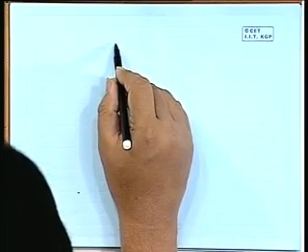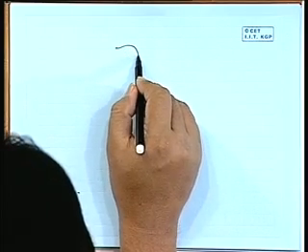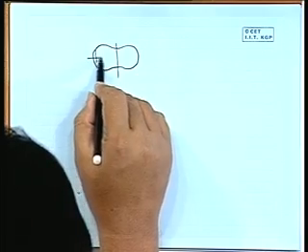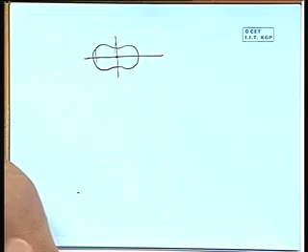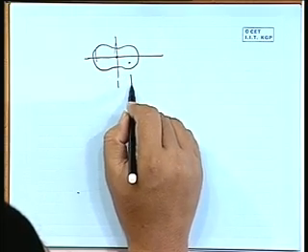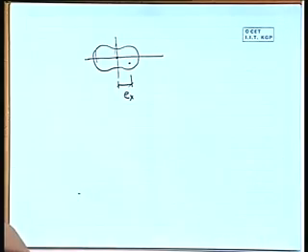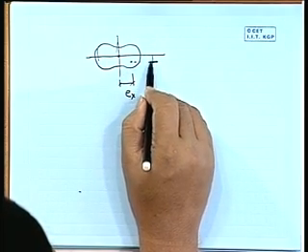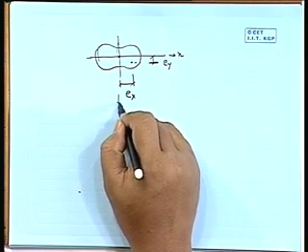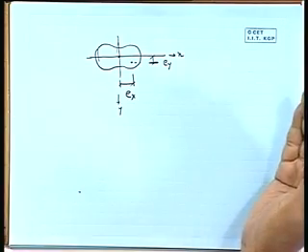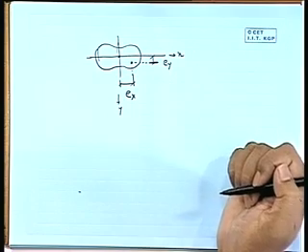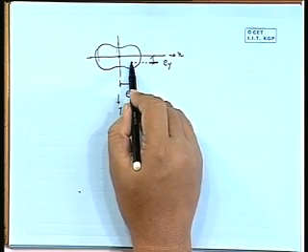Say if I take any cross section. So, any cross section is quite important here, I will discuss a little later. Say this is the centroid of a cross section of a column. Now, if the load is acting here, say this distance we can define as Ex and that distance we can write as Ey, right. Say that side if we write x and this side if we write y. So, along x the eccentricity we are defining as, say this is the load point. So, this is Ex and this is your Ey, right.